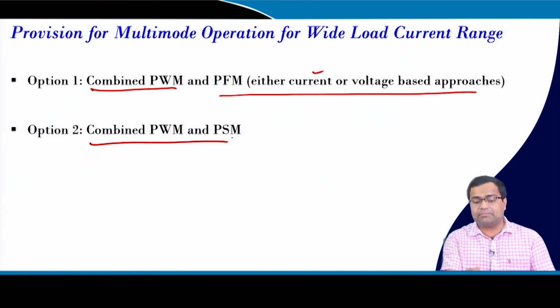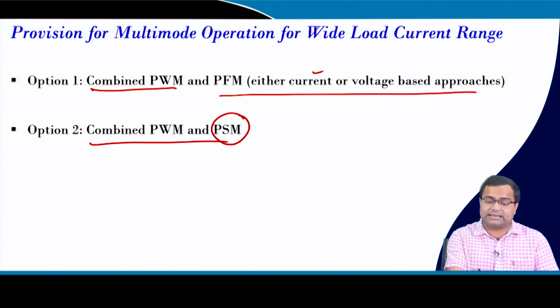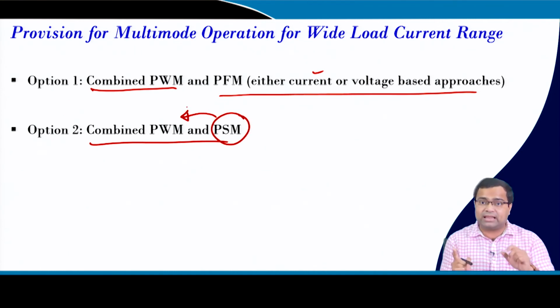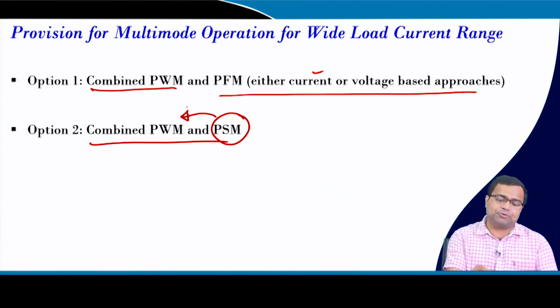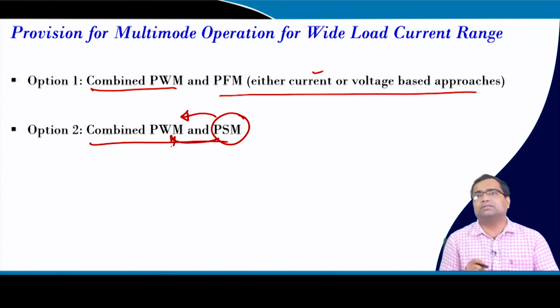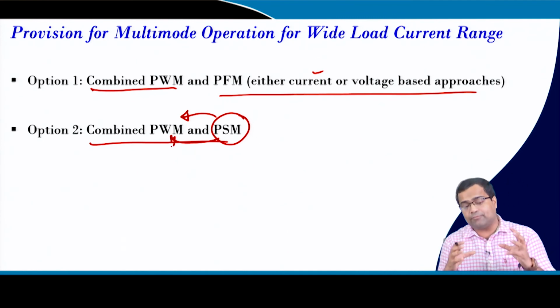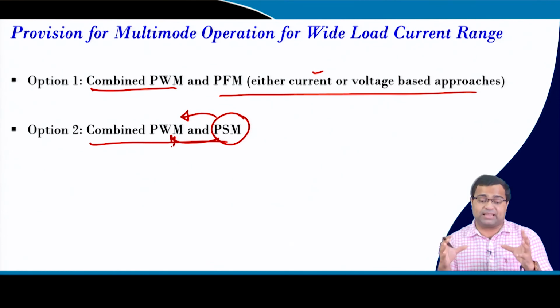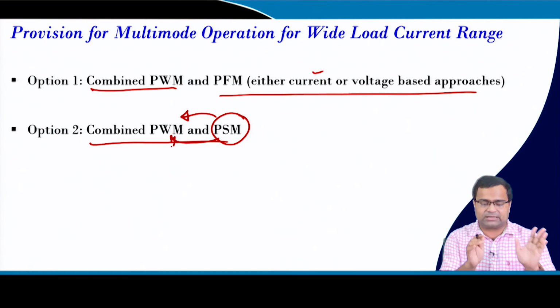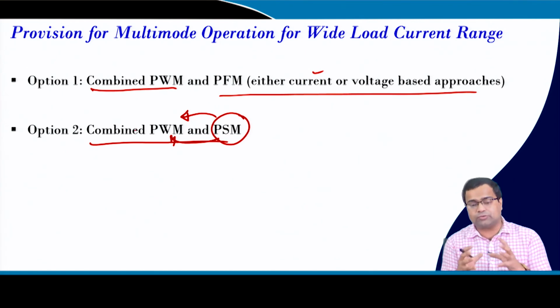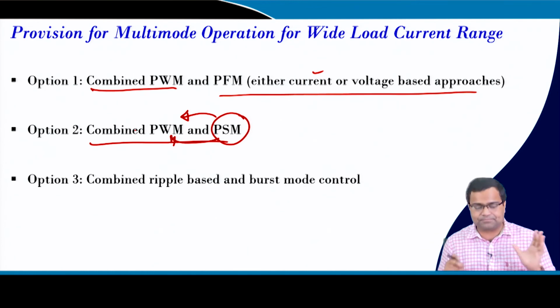So, the PSM technique is an integral part of PWM, we only have to enable the skip operation, and if you make the duty ratio of this PSM come from the loop, then it is a voltage control or current control PSM technique, and there are techniques that are proposed. We have proposed multiple techniques on that, so you can combine these techniques. So, this technique can also be used for a wide load current range.